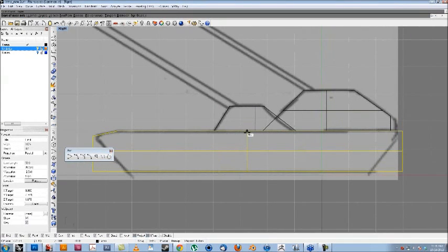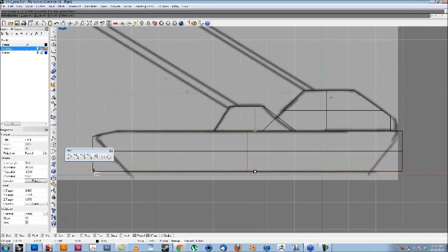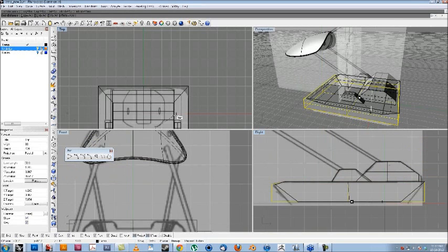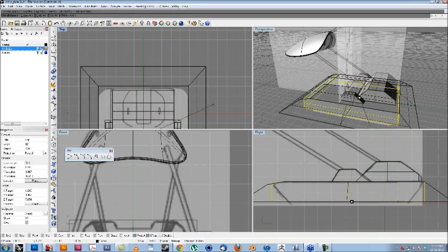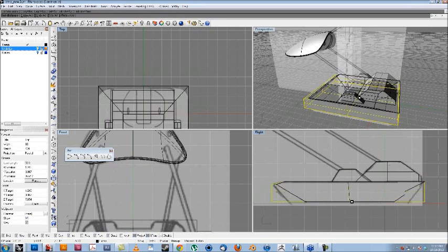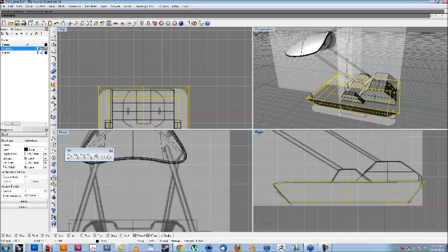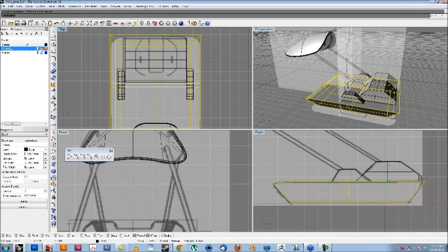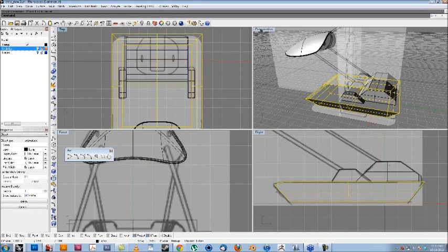So I'm going to taper this, middle's turned on. We'll taper it from there to there. And I'm going to turn infinite on. And now what this did was, you can see in the perspective window, it's actually tapering how I need it to be. So the whole idea here is to think about how your shape is going to work before you start editing it.